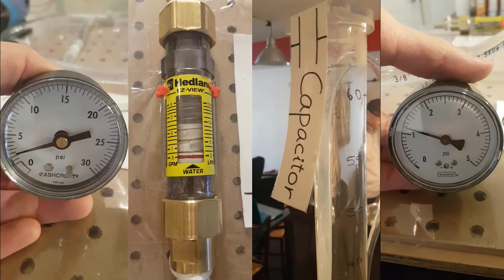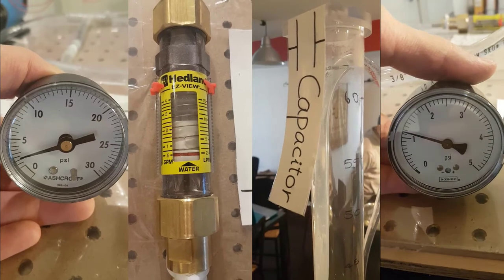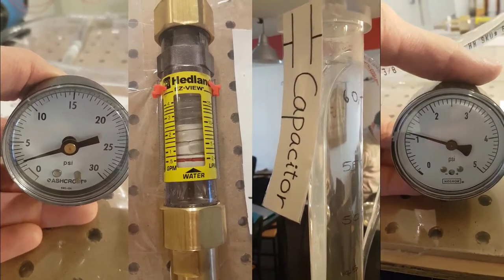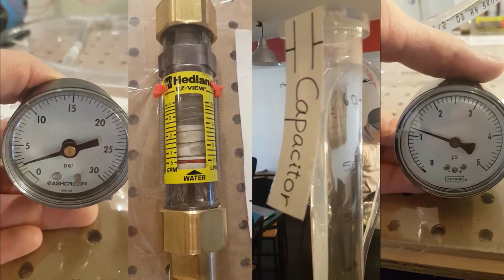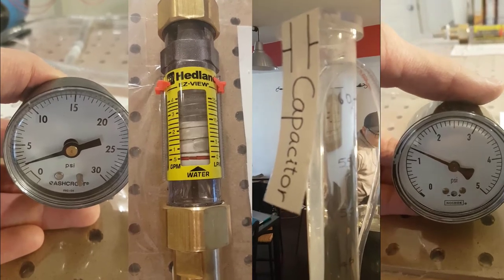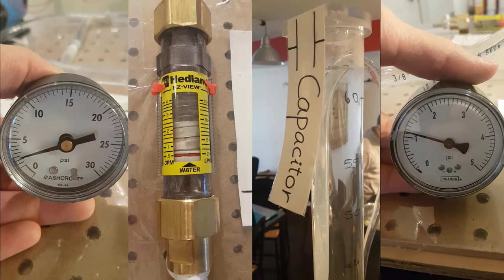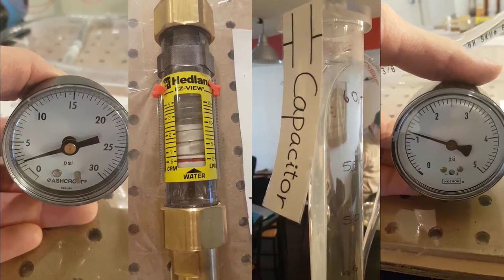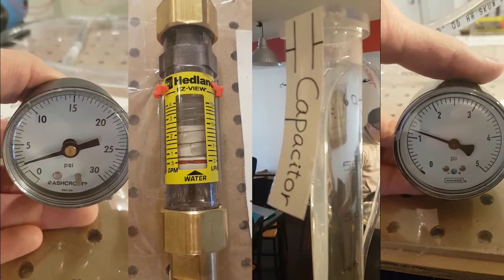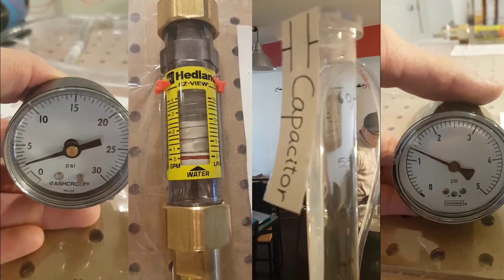From left to right, the measurements shown here show the input pressure, the flow through the inductor, the capacitor water height level, and the output pressure. This is the case for when the duty ratio is set to 0.5 and the frequency is set to 4 Hz by the Arduino. Notice that the output pressure is approximately half of the input pressure, which is 2.5 psi, which is what we expect from our equations.